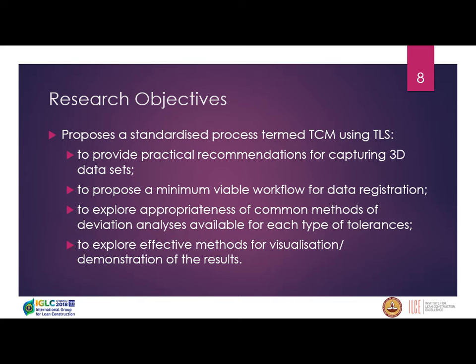Research objectives. We propose a standardized process called tolerance compliance measurement, or TCM, using terrestrial laser scanning, or TLS. As part of this paper, we have provided practical recommendations for capturing 3D data sets, how to practically capture data sets so that you can make sure your deviation analyses have a good level of accuracy.